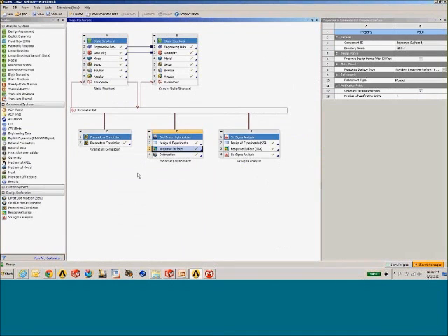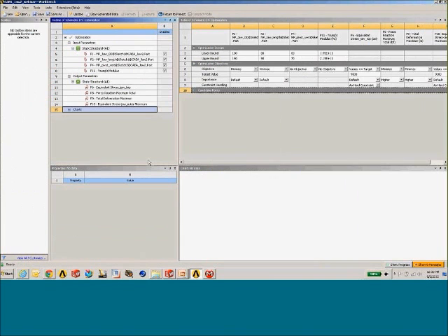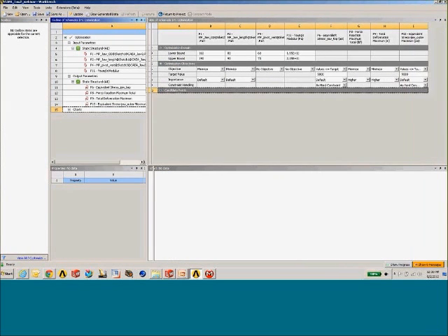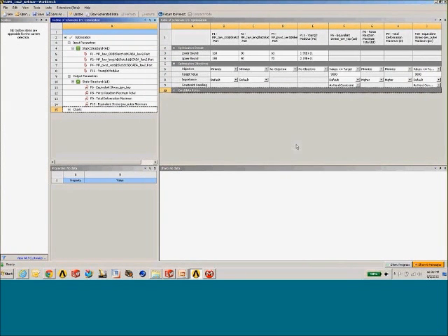With those polynomials, we can now do something called a goal-based optimization, where we come into our parameter list and we specify goals, and we'd like to find the best fit to that curve for our particular goals. So I typically start out with the output quantities. In this case, I've taken my two stress quantities and indicated that I would like to target a value that's less than or equal to a particular value, in this case 9,000 psi. When it comes to the reaction force and the total deformation, I'd like to minimize both those quantities, because this is a vice grip after all. I'd like to require a minimum amount of force to be able to generate as much clamping pressure as possible.